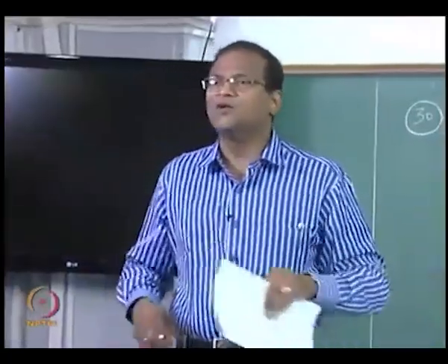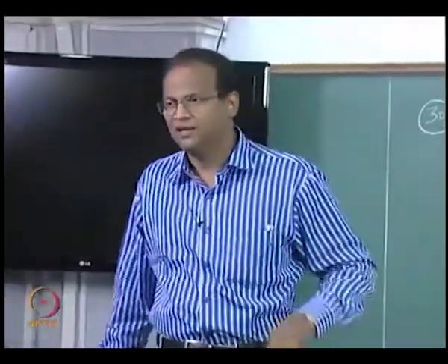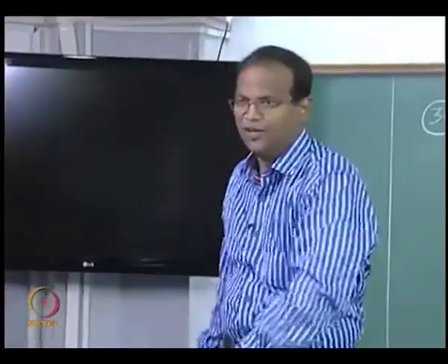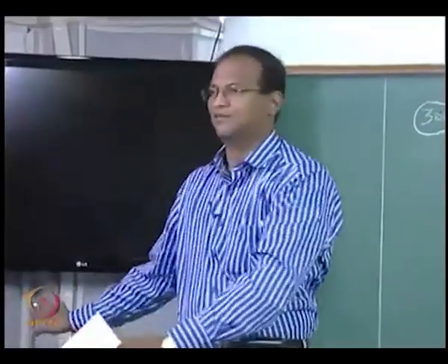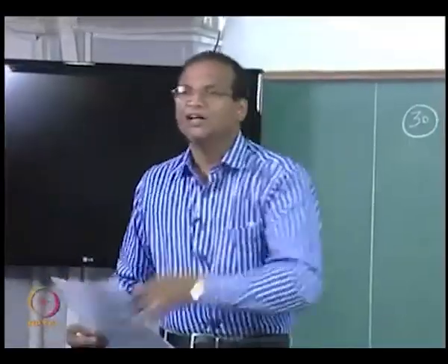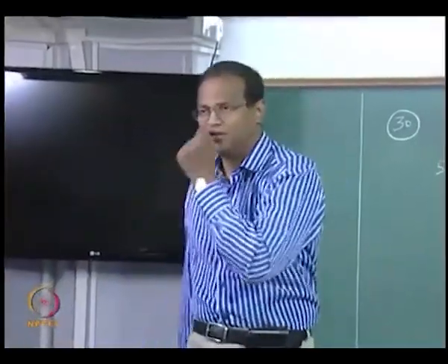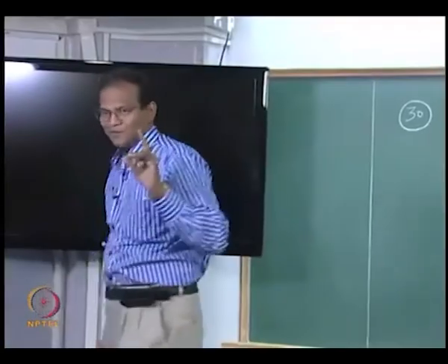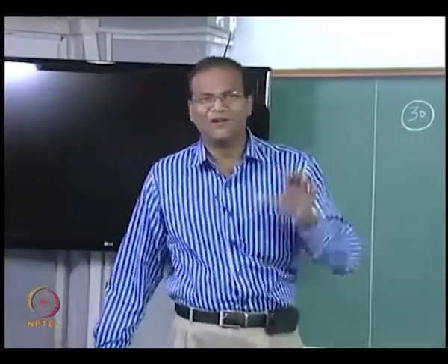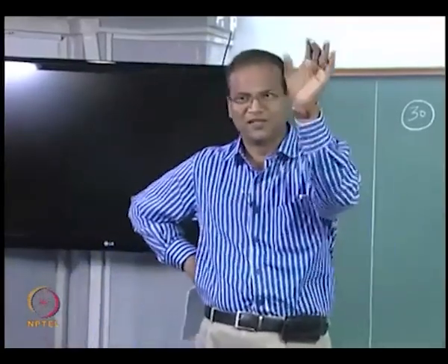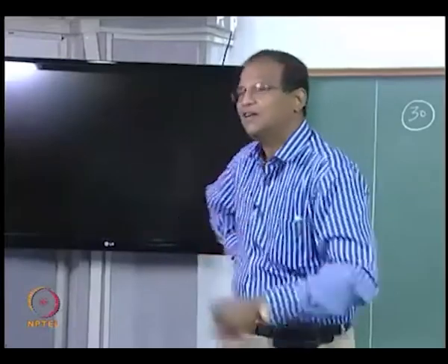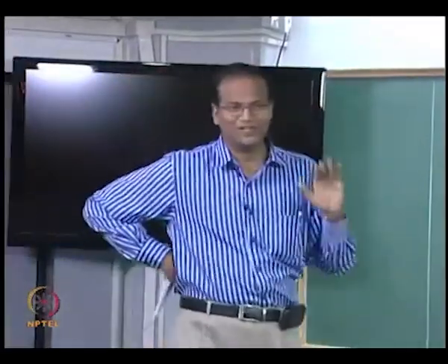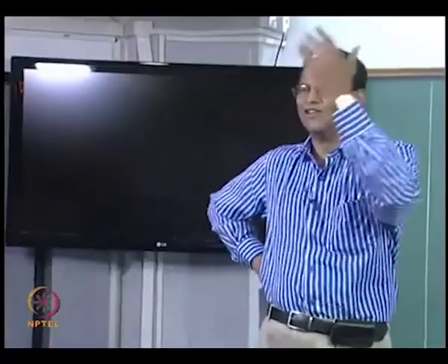The other risky route would be to disregard that completely. F1 2 3 4 is equal to F1 2 3 plus F1 4, you keep on doing till you get an expression for F1 2 in terms of all the other things, and then substitute A1, A2, A3, A4. This is high risk from a student perspective. It is better to just list out first the areas and all the view factors. At least the teacher knows that you know how to read the charts and get the basic view factors. Then you can start off with your algebraic manipulation.